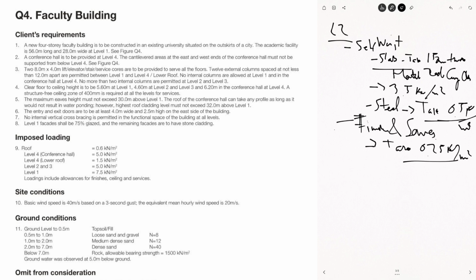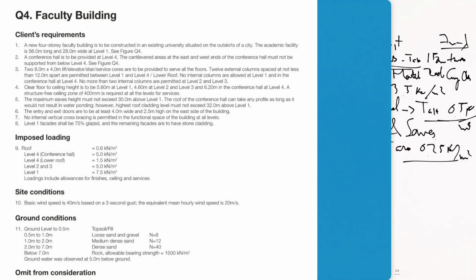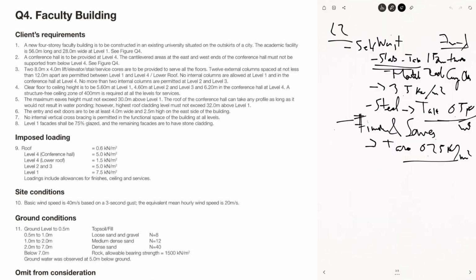But these values, like why did I take 150 for the slab thickness? All right, then I just say this is a typical slab thickness for a span of, and whatever my span is, I think is about 6 meters or 7 meters. So I can take that one, and then I don't have to prove that one because it's not the principal or primary structural element.